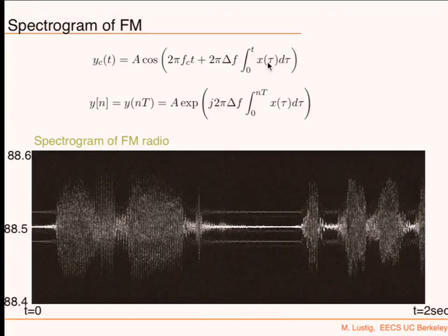You take the derivative of the phase, you get 2 pi f, which is the angular frequency. Okay? So the derivative of the phase is always the frequency. In this case, the derivative will be 2 pi delta f, which is how much you're willing to deviate, multiplied by your signal, which then looks like this. Okay? Does this make sense?